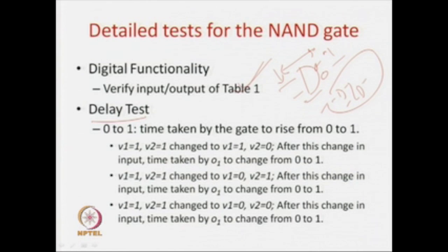But in case of a VLSI circuit like a NAND gate, digital functionality is one, and the other very important test you have to do is the delay test, because unless you say what is the time required by this gate, nobody is going to accept the design. When he is plugging your gate into his circuit, he should also know the amount of time required by that gate to give the output. Accordingly, he can go for his design, because when he is shipping his product, digital functionality as well as your performance in terms of speed is very important.